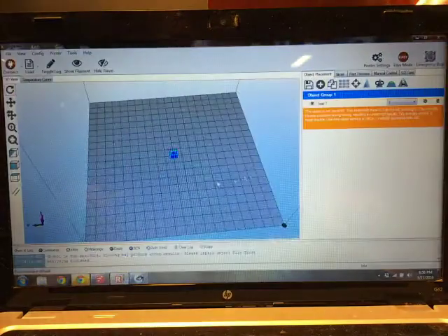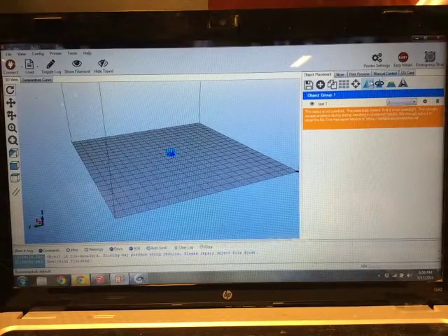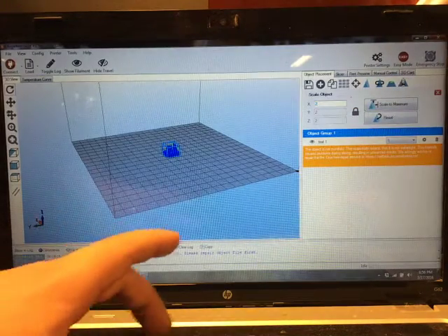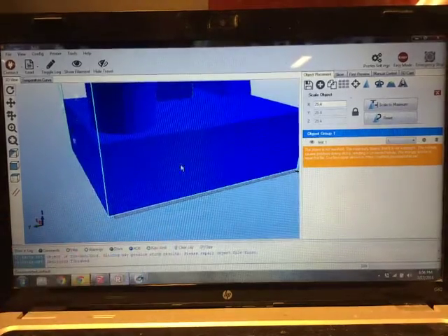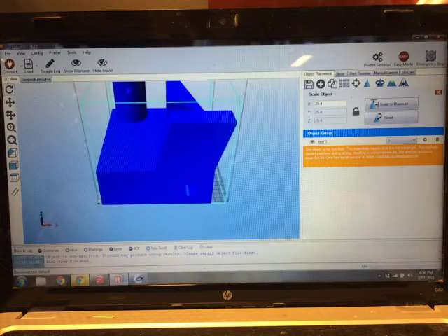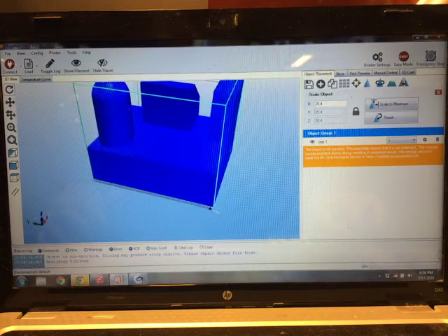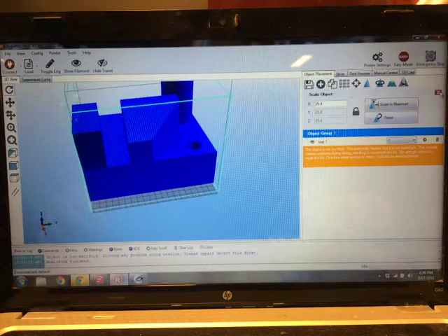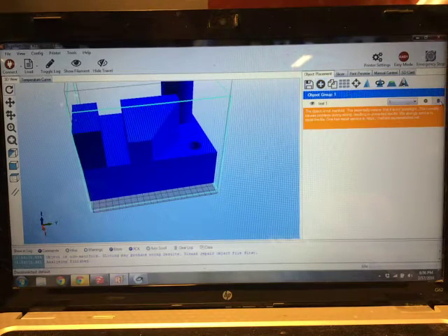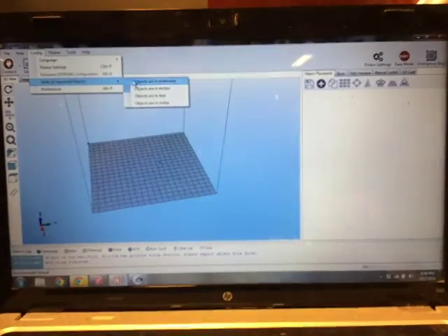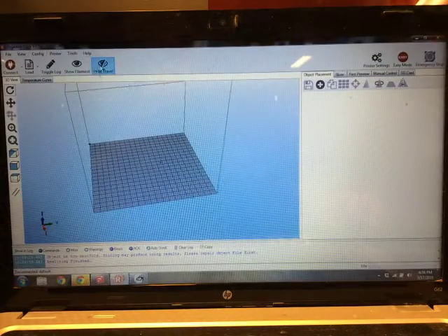Alright, so back to Repetier Host. This thing's tiny. So you can either scale it in Repetier Host to the same exact thing, 25.4, and you'll notice it's just a little bit longer than the bed, and so it's supposed to be like 167 by 208, something like that, which is ridiculous, but whatever. That's how we drew it. So you can delete the object with that, and then I think the printer was set up in configuration to be in, okay, let's go back to millimeters.